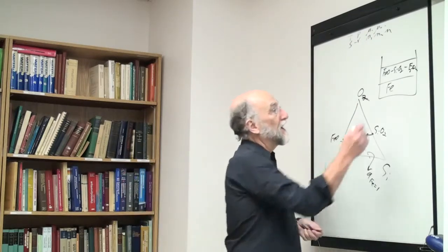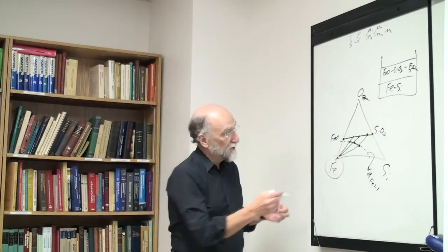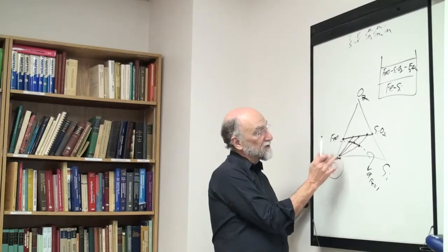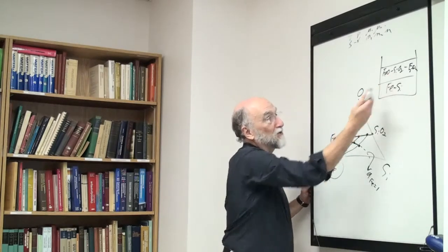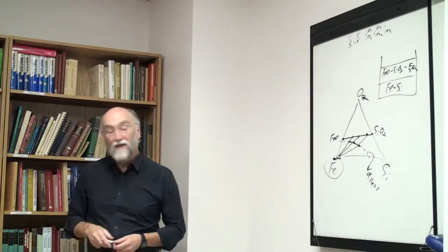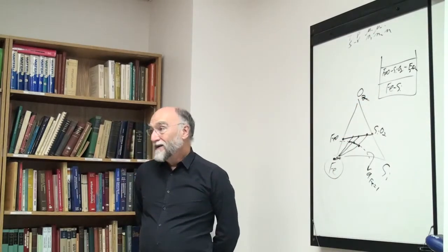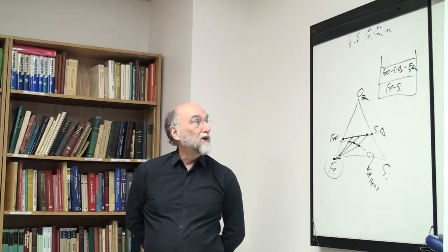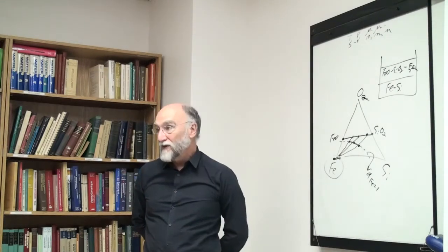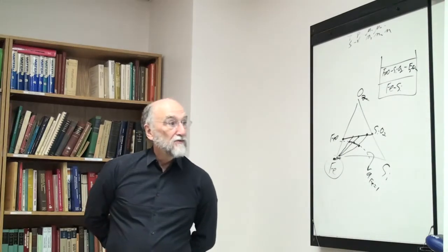Okay, but in reality, the iron is going to contain a little bit of silicon when the thing's reached equilibrium. Okay, so this isn't really what you're doing in the real case. What you're really doing is you can't keep it in equilibrium with iron. You can't practically keep it in equilibrium with iron at one unit activity. You can only keep it in equilibrium with an iron silicon alloy, whose content of silicon is going to be determined by the exchange reaction between the phases. In the case of this particular system, this is very close to